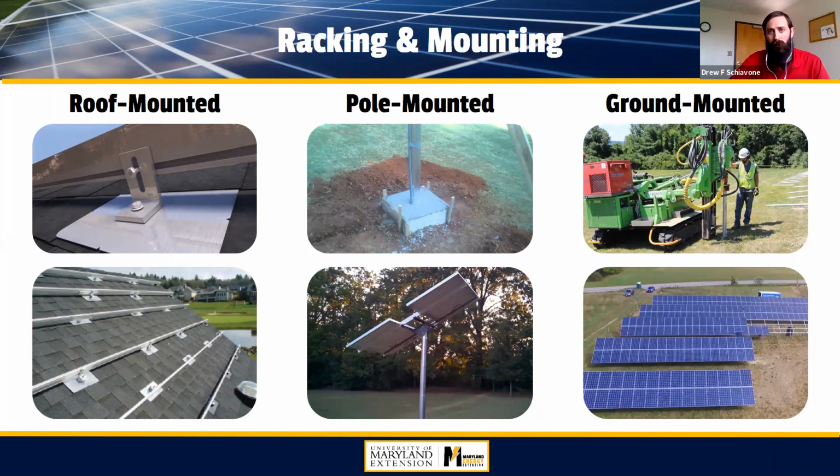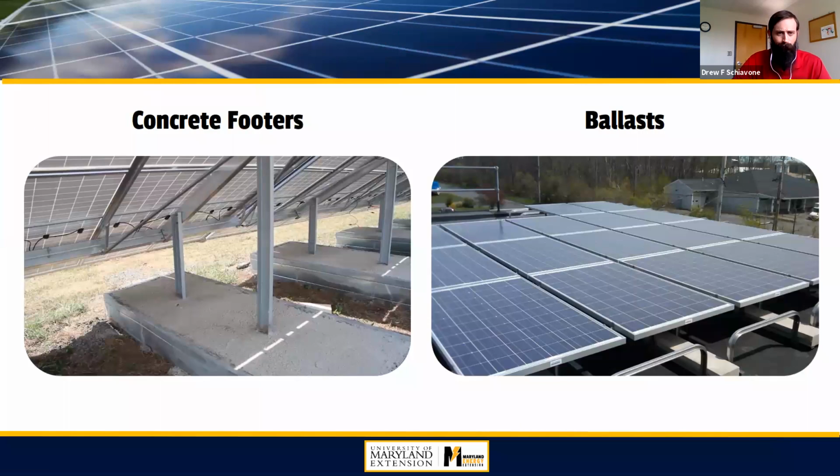Ground mounted systems, and I'll kind of touch on some of the larger projects, not necessarily utility scale, but it could be. These systems are commonly, nowadays, using a pile driver or some kind of screw system to drive the post down into the ground, and then you build your framework on top of that. There's other options as well, concrete footers, and that used to be kind of a standard with a lot of companies using concrete footers. For these, it is a bit more expensive than the pile driving systems I just mentioned.